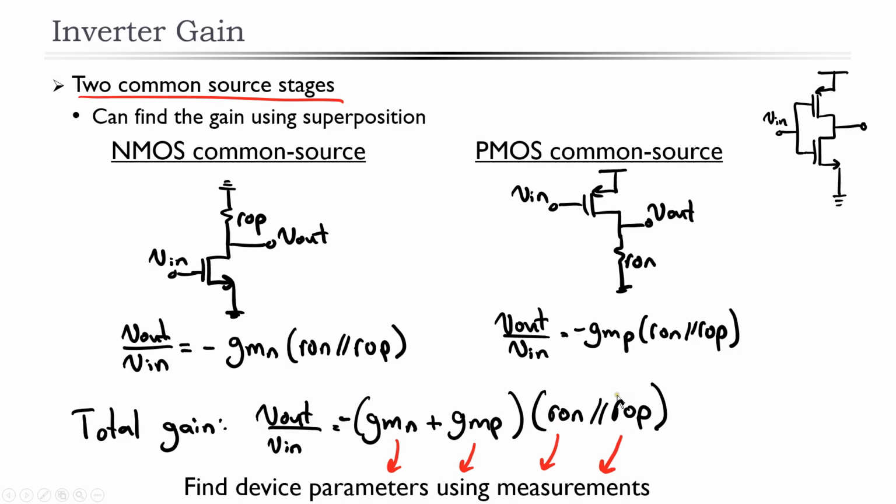So this is really an interesting effect that's happening here, because it means that both the NMOS transistor and the PMOS transistor are contributing to the overall gain. So we're actually getting more gain as a result of the fact that both of these devices are active at the same time. So this is going to definitely increase the gain of the circuit.